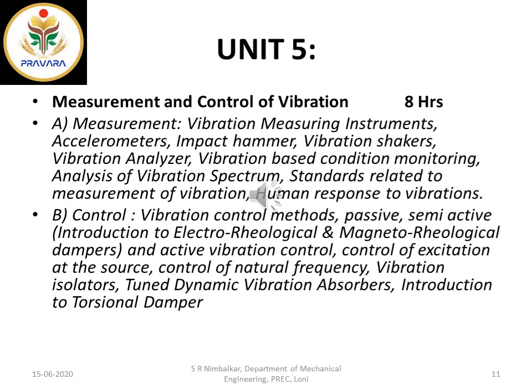Basically, when you are controlling vibrations, as I explained, vibration is a motion, and motion is a form of energy, kinetic energy, isn't it? So when you are damping it, damping is nothing but resistance. The way of applying resistance to this motion is one kind of controlling the vibration. If you see the shock absorber in your two-wheelers, whatever shocks are coming from the road, because of the shock absorber a lot of the vibration energy is absorbed. So whatever energy is in that motion of vibration is absorbed.